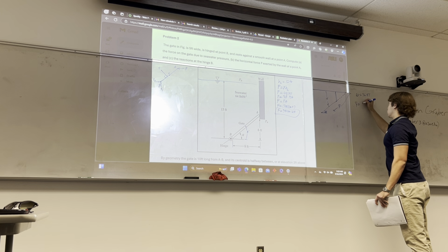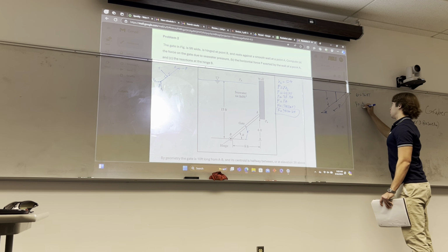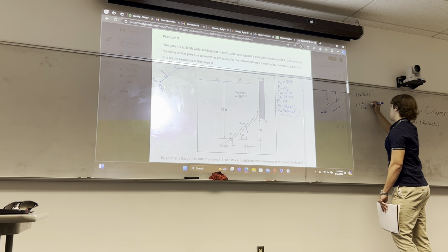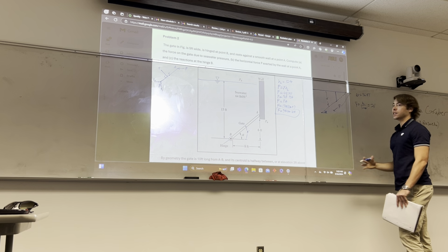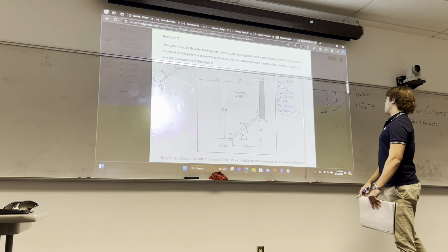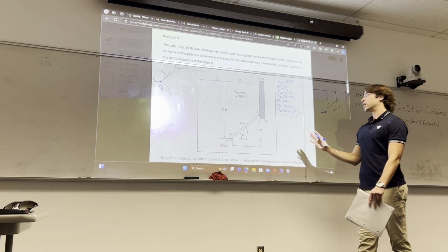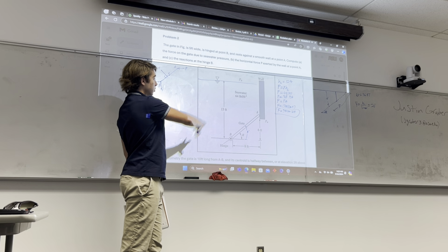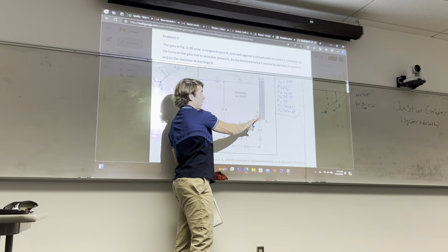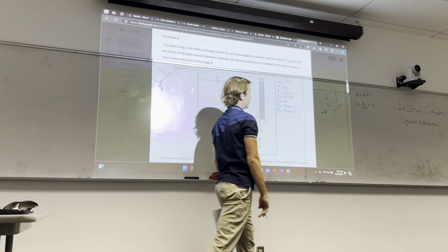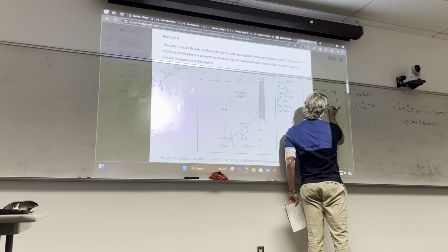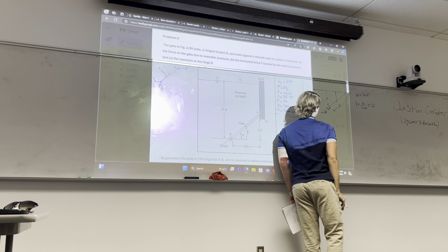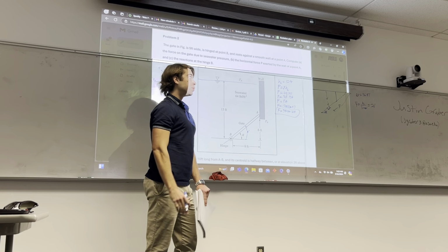This y bar equals hc over sine theta. That's just trigonometry, you can go into that stuff if you really want. Anyway, you get y bar equals about 20 feet. It's like 19.999, blah, blah, blah, whatever. Okay, so cool. Now we've tilted this on its axis, so that's good. And so now we've got it in terms of the actual plane that this is sitting on. So now we want to find this little tiny distance, and we call this little length L right here. That defines the distance we're moving down.